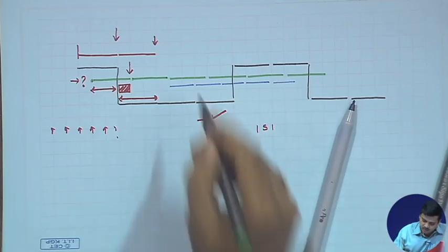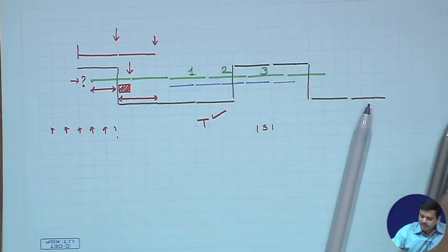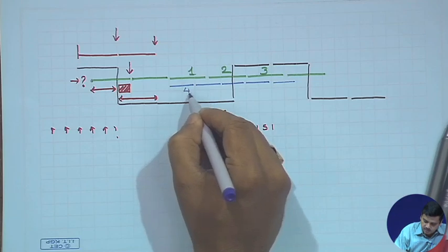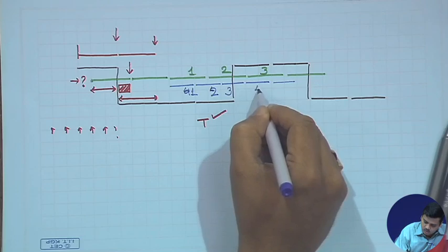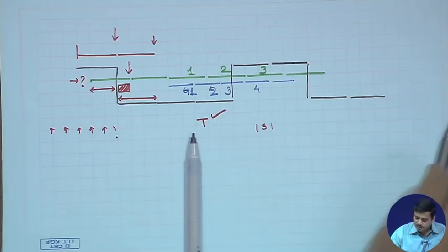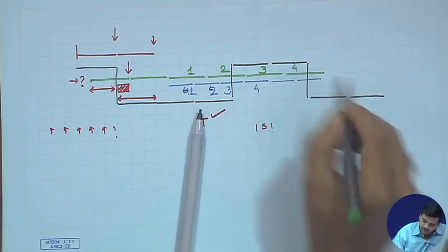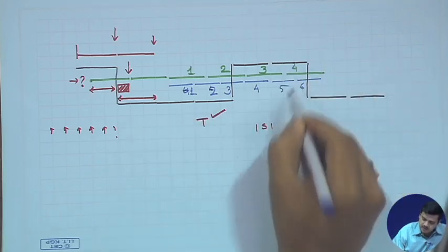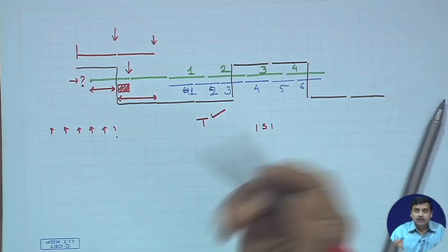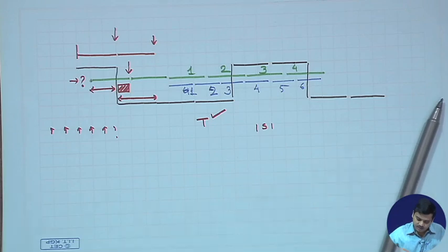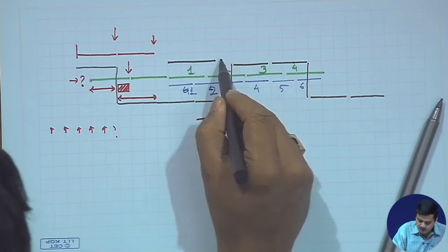So, there are 1, 2, 3 symbols which have been sent from the transmitter, but the receiver records 1, 2, 3 and 4 in this time interval. So, if you record all of them, there are 4 symbols which are sent and the receiver records there are 5 symbols. So, obviously, there is going to be a huge error. The reverse could also happen, that means the receiver has a clock which runs slower, that means the time interval is larger.